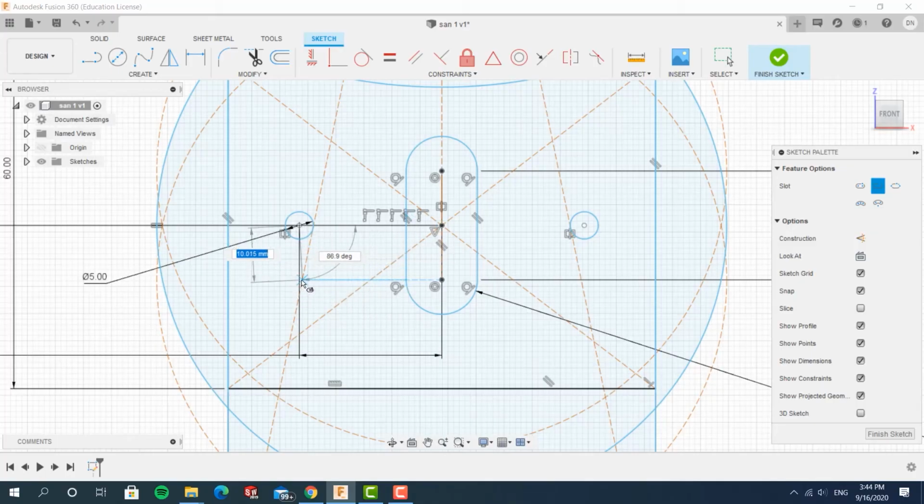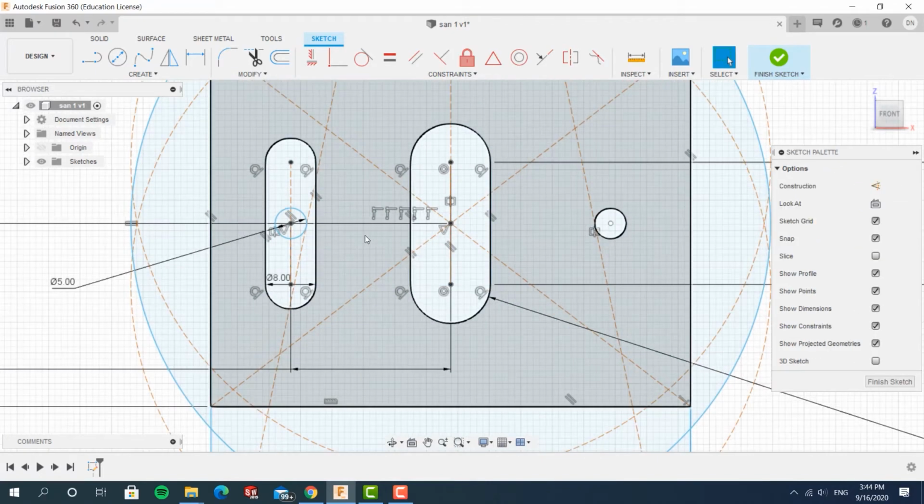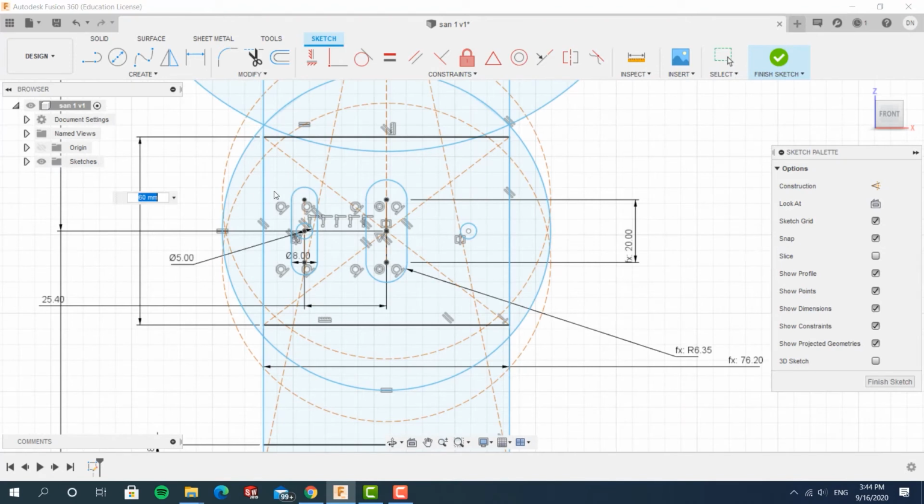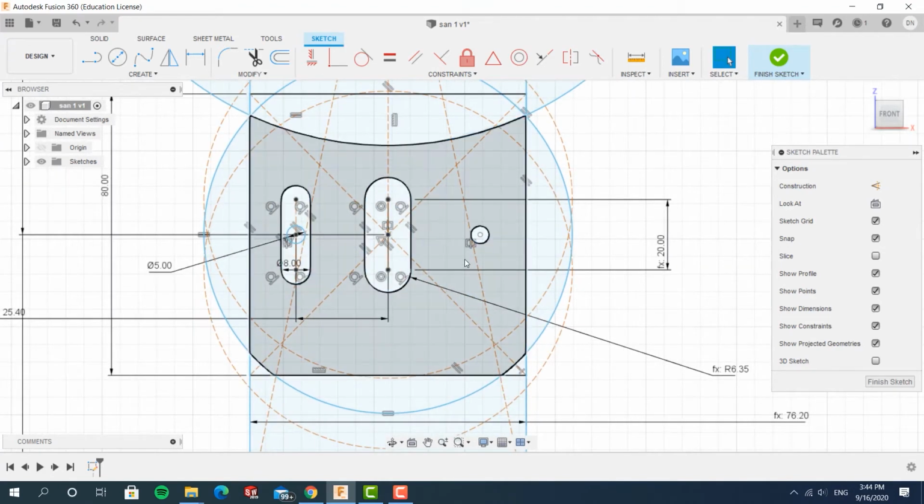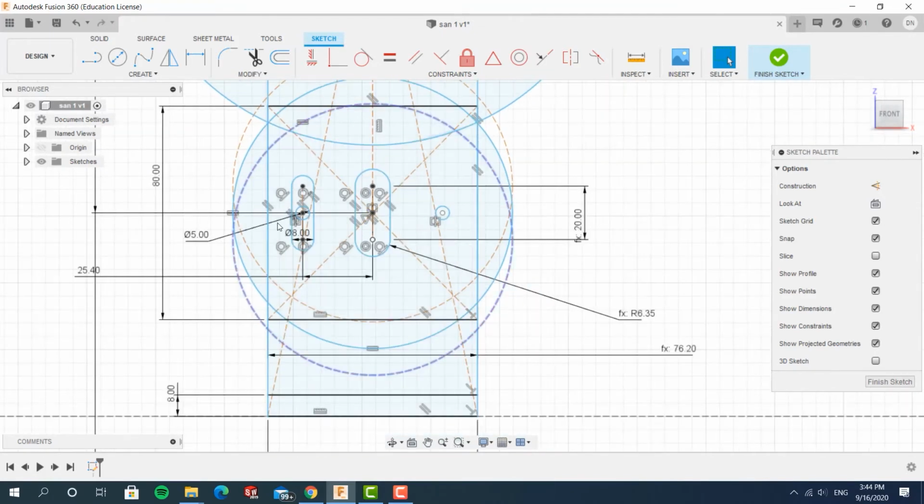Okay, as you can see here, when drawing out the slots, there are a few things that you need to consider. First, you would need to consider the size of the small piece of aluminum so that it can fit all of the slots without deforming too much. Your motor is going to spin a whole lot. It's going to work for a long time. There's a chance that it will deform the metal, and you don't want that to happen.